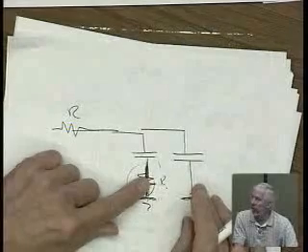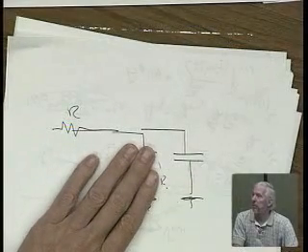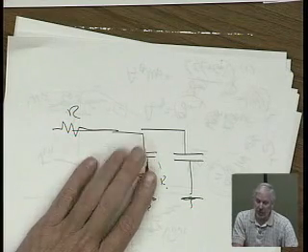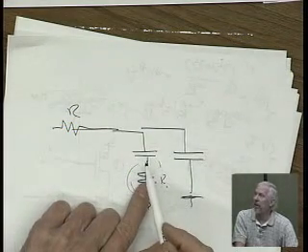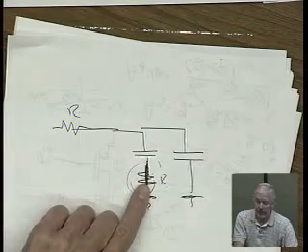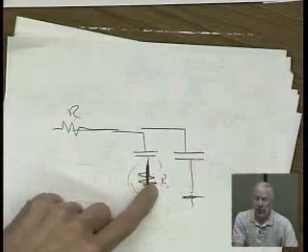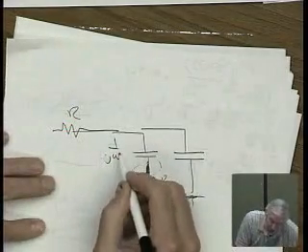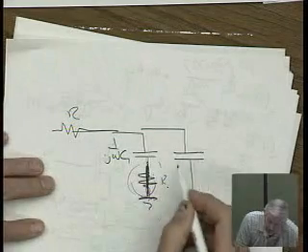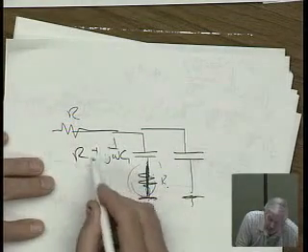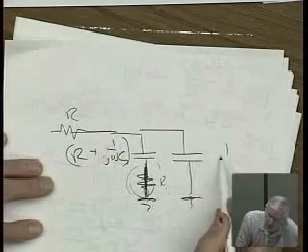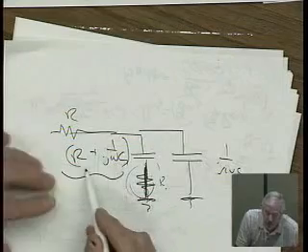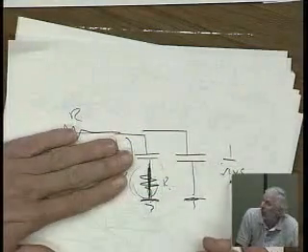In fact, if this gets larger, this capacitor becomes less important. I don't even need to put that in there. So this capacitor has less effect. The capacitance doesn't change. It's just, if there's infinite resistance here, what would happen? It's a parallel combination, right? It's 1 over j omega C plus R in this leg, and it's 1 over j omega C in this leg, and so you have a parallel combination of all these things. Once this leg gets to be very large, it's unaffected compared to these other ones.